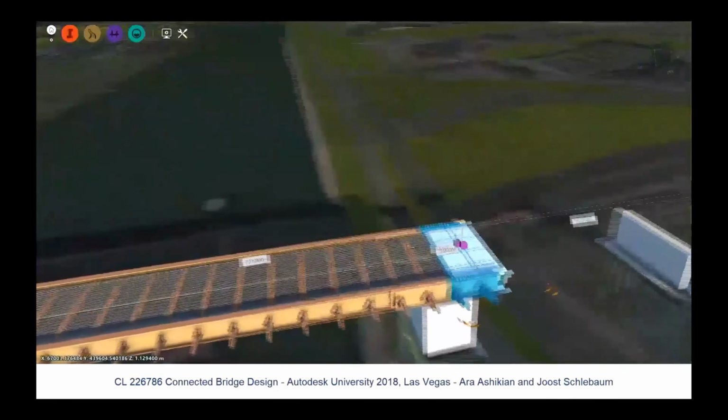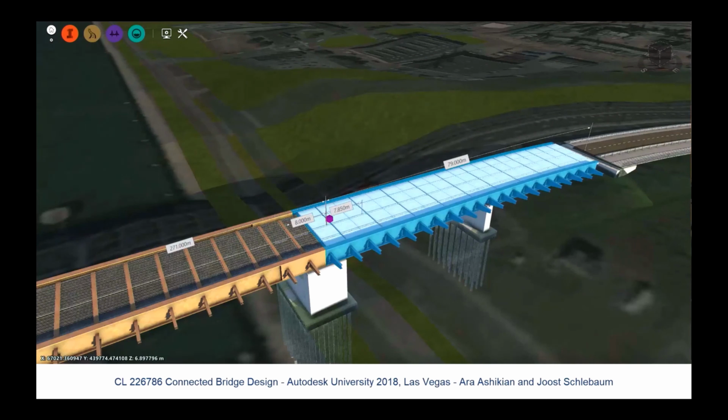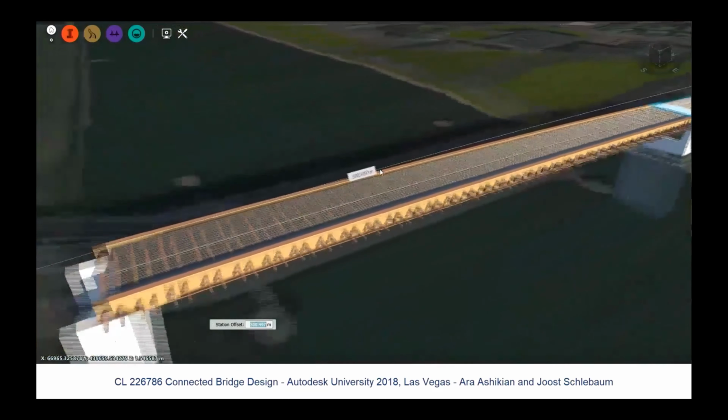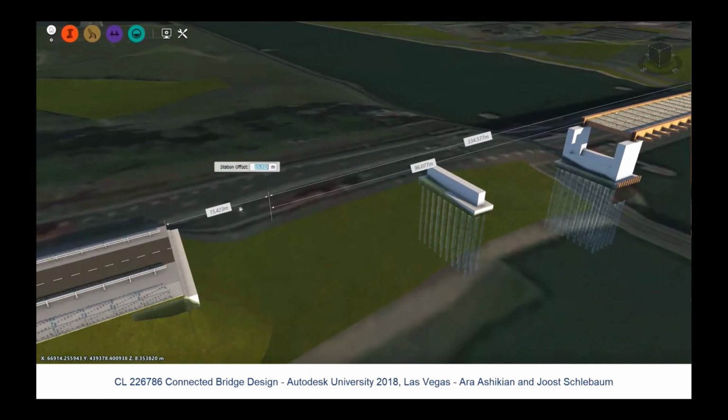So here I'm going to use the set. Now, I only spent a day or two on this. If I were to spend longer, I would have added a bit more logic, with the option to have curved and planar edge girders that follow the super elevation. All of that's possible. It's just different parameters that you expose in there. So quickly, literally in real time, you're modeling the geometry. And as a bridge engineer, not as a computer scientist, I'm placing it, clicking it.